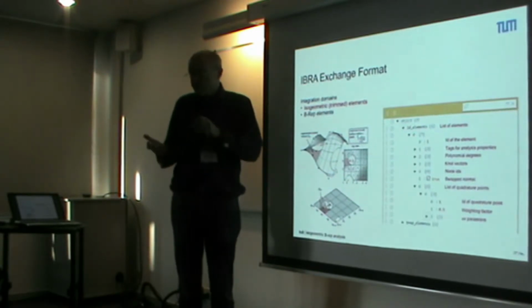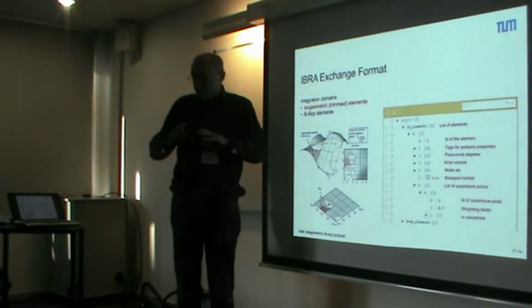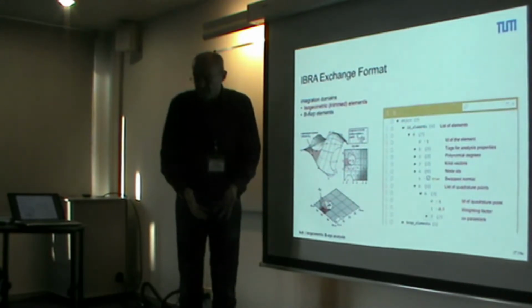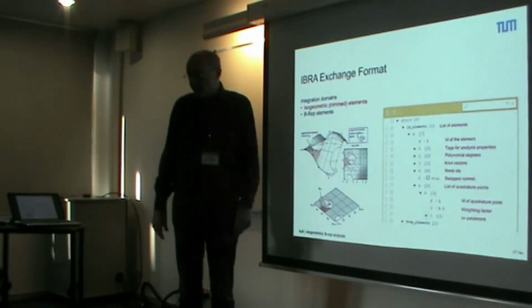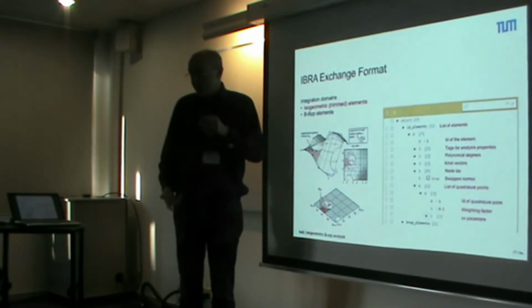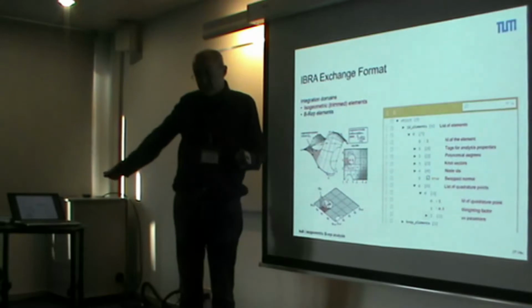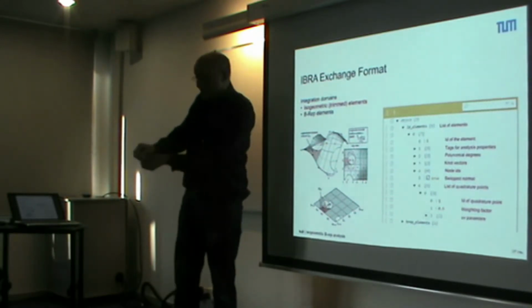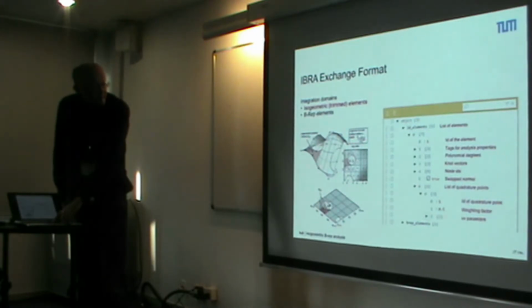And by that you turn the typical finite element program upside down. Instead of formulating all the elements and going down into the Gaussian points, you just go through the loop. You just have a list of the Gaussian points which you operate on, and get from each Gaussian point all the necessary information regarding geometry and the ansatz functions and whatsoever.